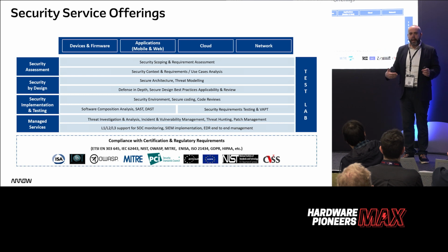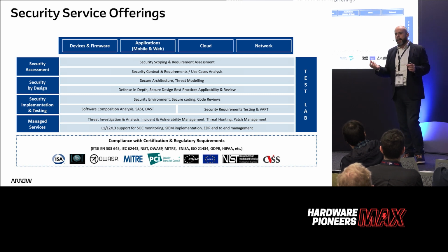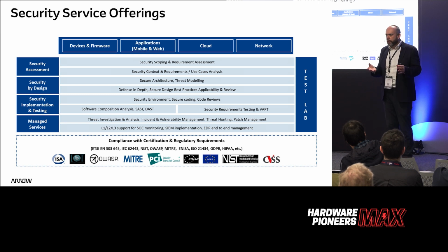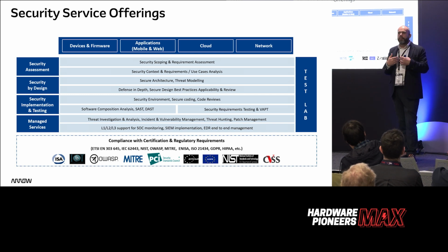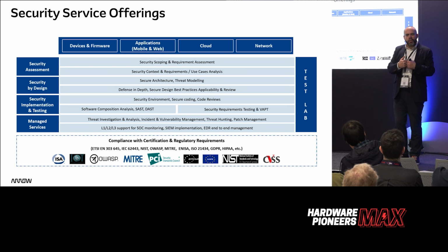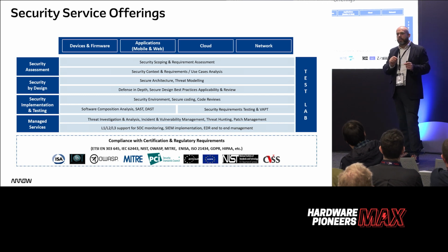That will then give you the time to consider for your future products, do you want to do it in a more BOM efficient way? And when I'm talking about these secure enclaves, we're talking about in small volumes adding maybe £5 to the cost of your design, which if you're in high volume is a lot. Obviously, high volume prices will be different. And to me, I almost don't like the solution because it's not as neat as using the features already inside the processor that you have. But it does allow you to resolve this problem across all of your products for one opportunity cost.